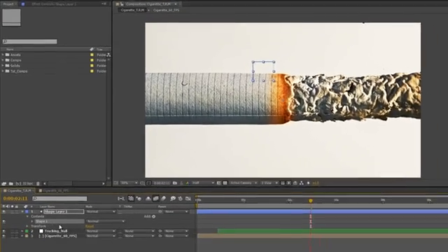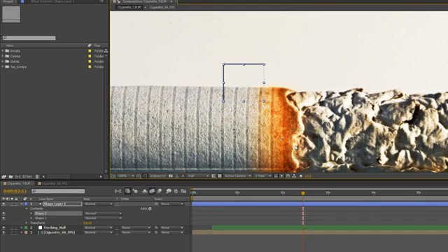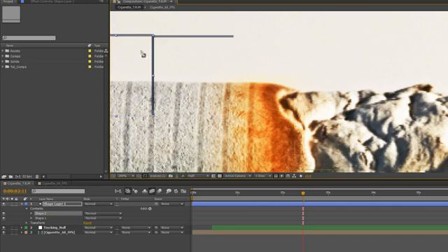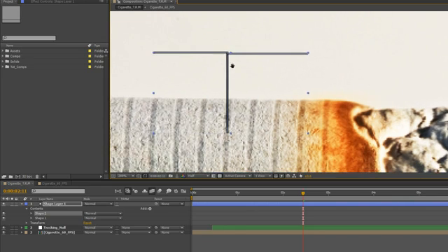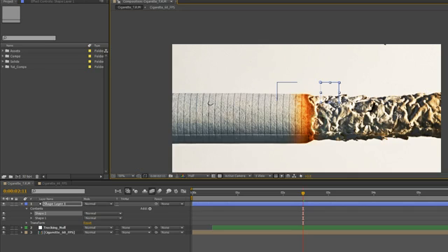Let's duplicate shape 1, move the anchor point to the corner here, and rotate it. By holding shift, I'm making sure every turn is 45 degrees, so this is 90 degrees, and just making sure it's in the exact position, and drag it back to somewhere around here. Maybe this one could be a bit closer as well.